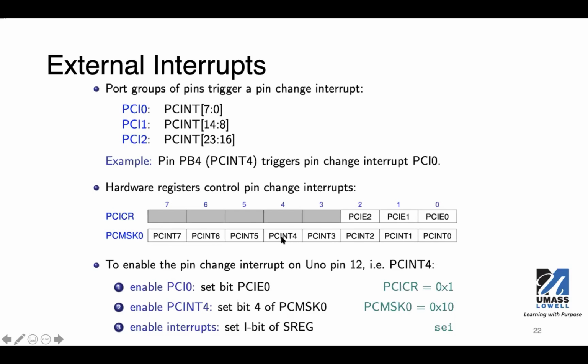So this is the 1. This bit location will be a 1, and all the rest are zeros. So we only consider this pin, and we ignore the other 7 pins. Even if they have any voltage change, they will not generate an interrupt. Only this bit will generate an interrupt.